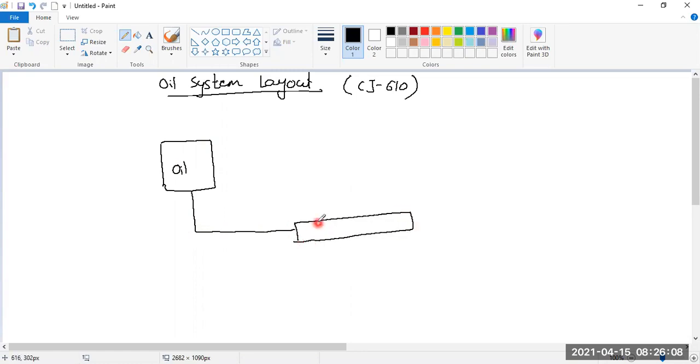So the oil goes into what? Pressure pump. I'm writing here PP as pressure pump. This part here is a scavenger pump. We'll come to the scavenger part later. Just understand, oil comes over here and oil is going into what? Pressure pump. Pressure pump is the same type of gear pump which we studied. It creates the pressure of the fluid.